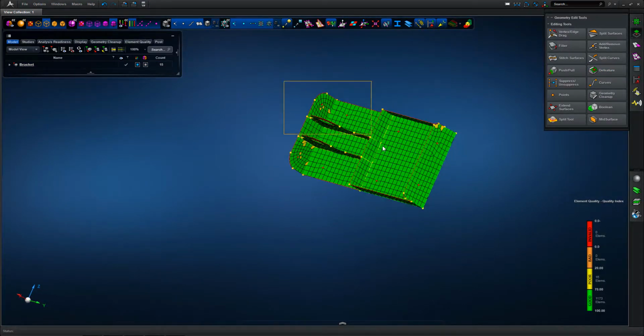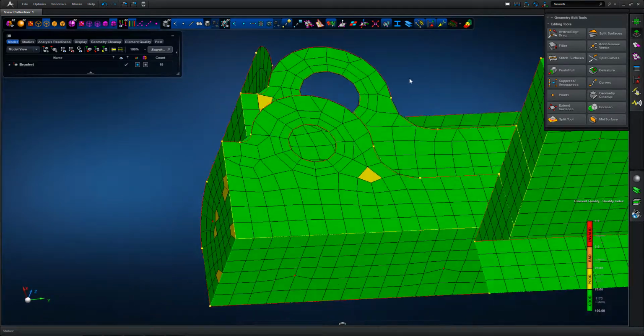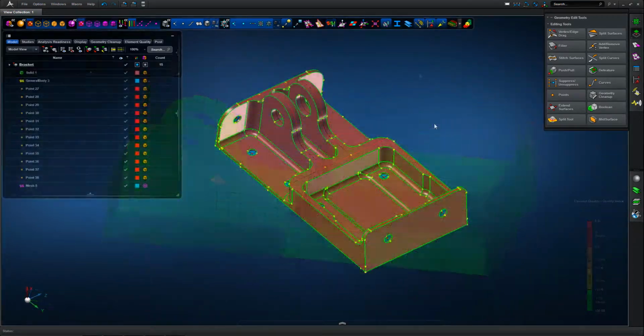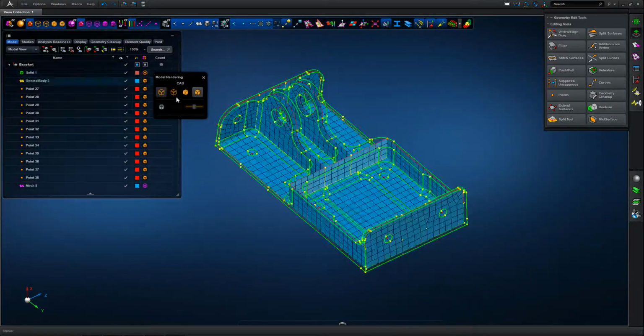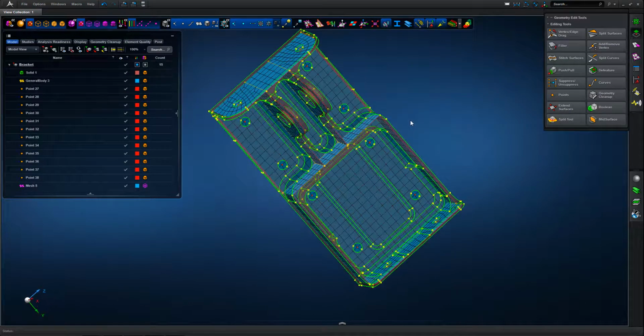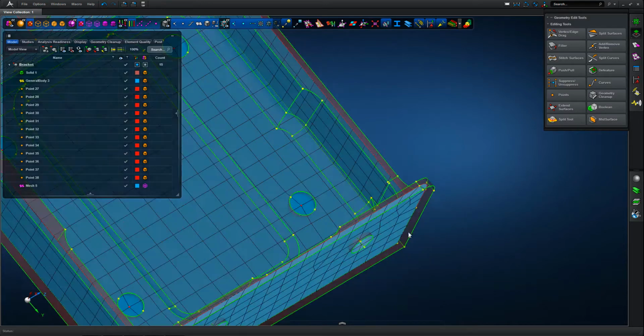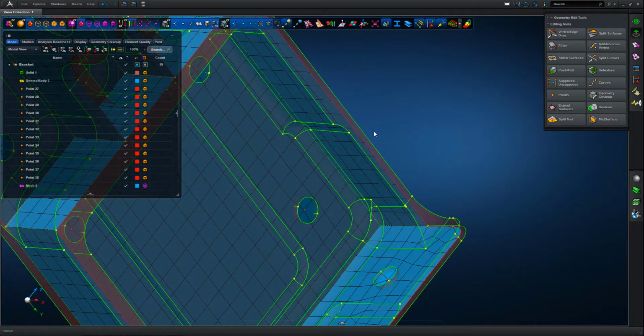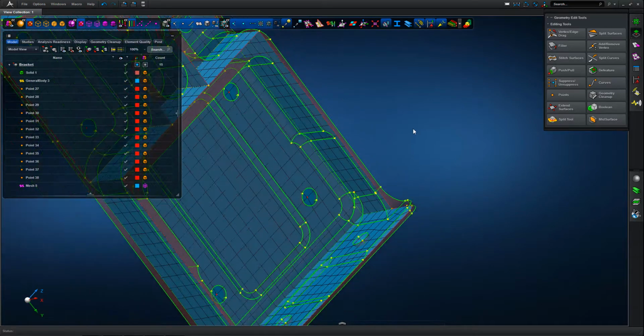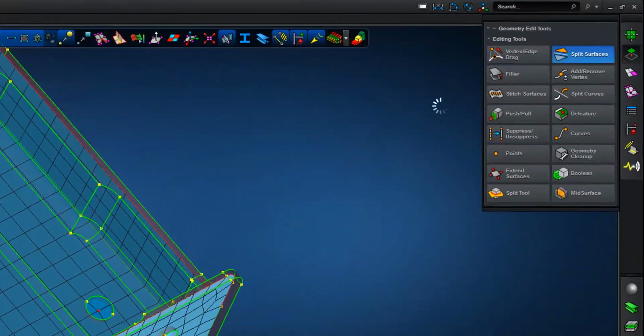If you notice, we haven't had to remesh any geometry because of Apex's generative approach. We can see that everything's updated automatically and washed downstream through the model definition. So putting the underlying solid back on again, we're now going to use this for some local edits. So we can see here there's a thicker region with a fillet which we need to respect within the mesh.